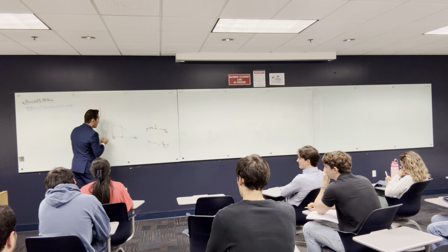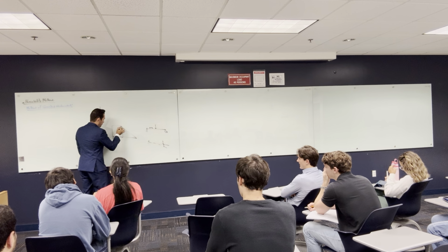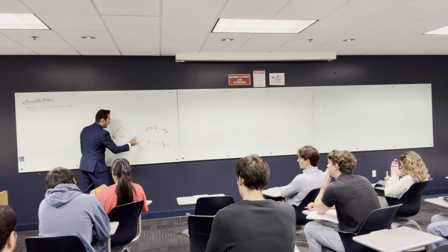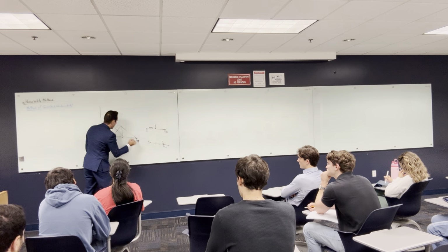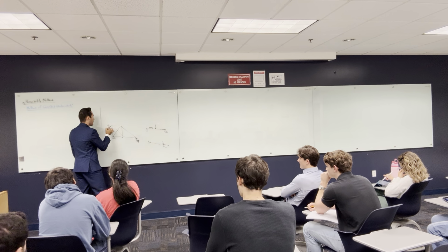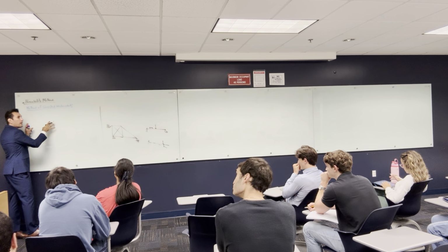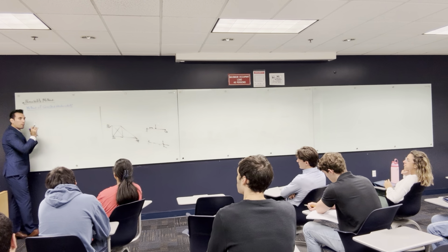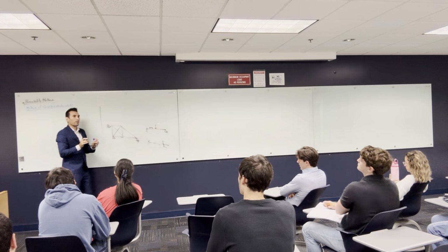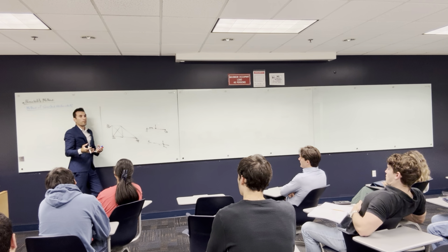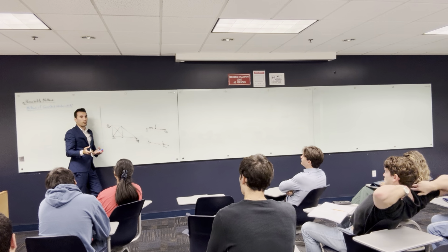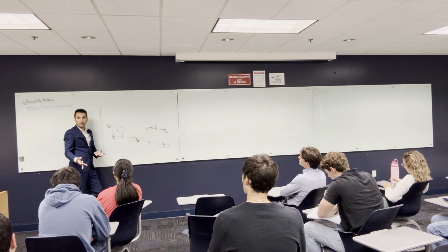And we had, I believe, something like that. Let me put a roller here, and maybe I put another roller here. Because the main idea of this method, number one, is to find what the redundant forces are. Because our problem with an indeterminate structure is the redundant force reaction. We need to find them.